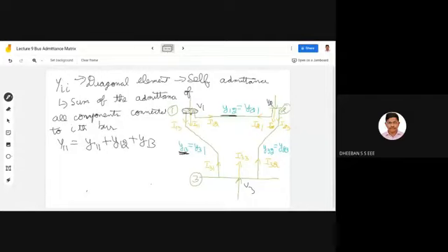So as per that, you will be getting this matrix, and there's a generalized formula for that. With respect to your second bus, it will be Y22, and here it will be small y21 plus small y22 plus small y23. For Y33, it will be y31 plus y32 plus y33.